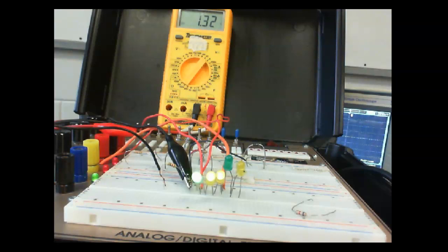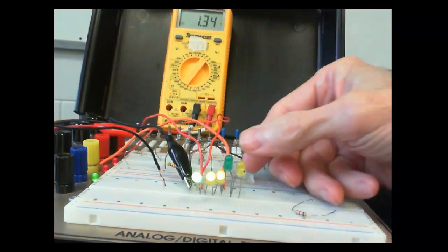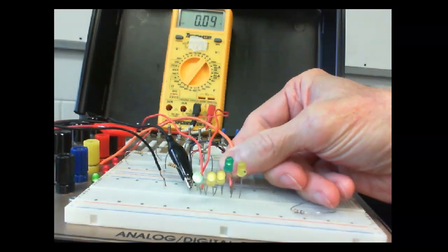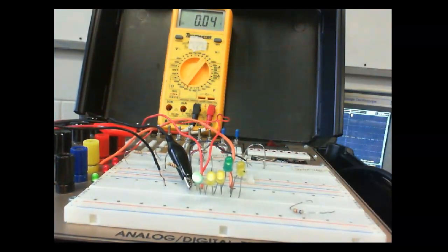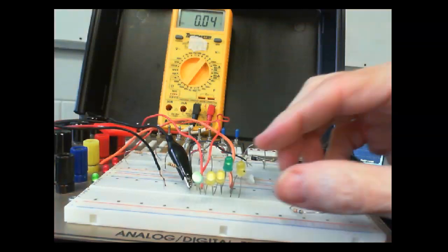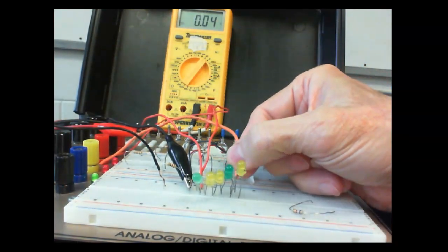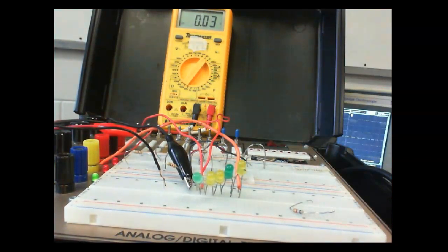So we're in the what? We're in the active region. So what the transistor's doing is automatically changing its internal resistance to keep a constant current flow. I'm going to come over here and add another LED. Of course, we're at the limits. Now the transistor's saturated. Can't get any more out of it. Right? So if I add one more LED, they all cut off because now we're not getting enough current flow to the diodes. But see, this is a constant current source. I mean, y'all understand that.